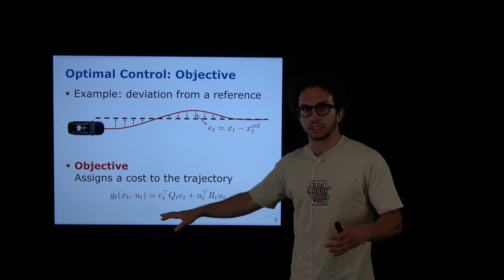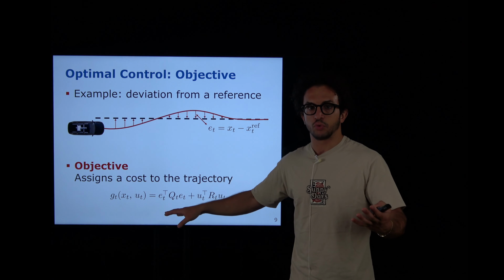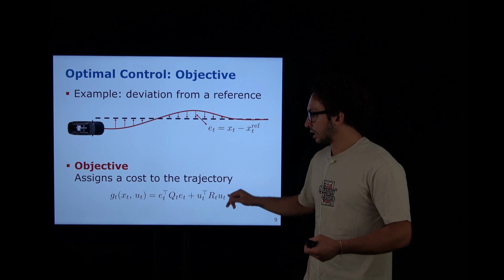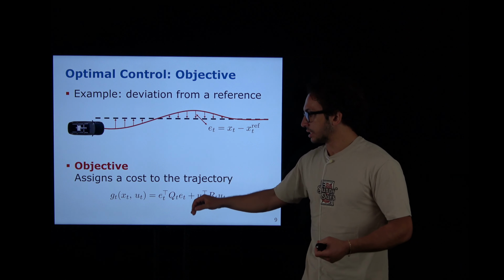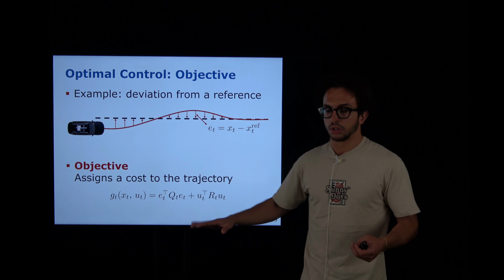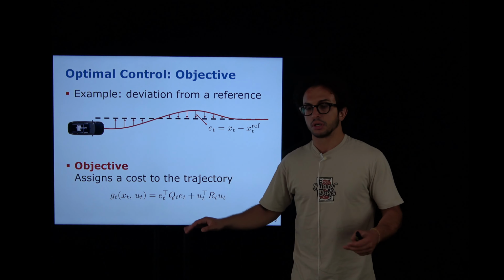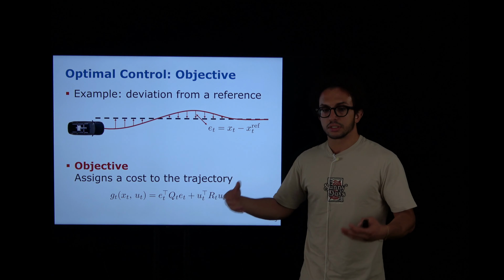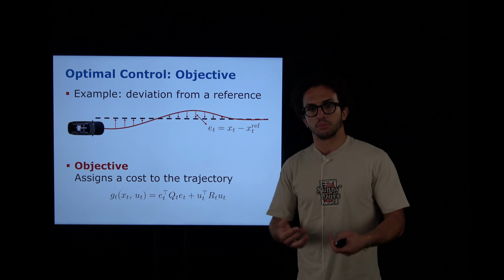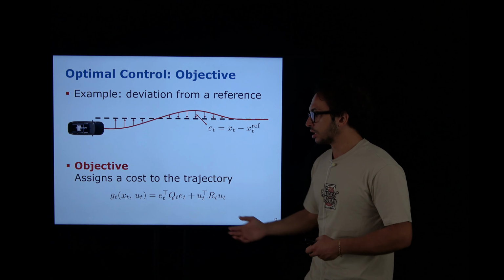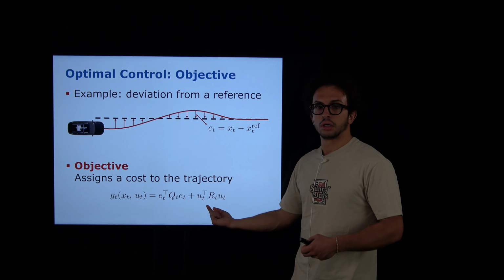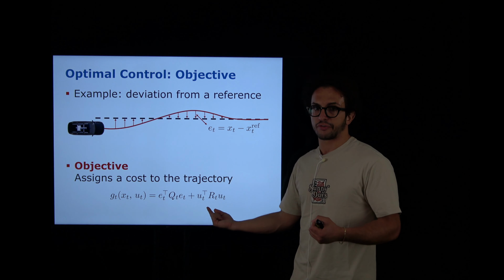Good. This is something that we know, as I said, we can achieve with PID control. But also, I want to minimize this thing. And now notice that this is the input. So the R and Q, just for now, they're just matrices. So U is the input that is given to the system. So we want to minimize also the input. So basically we are trying to have zero error by having a low actuator effort.